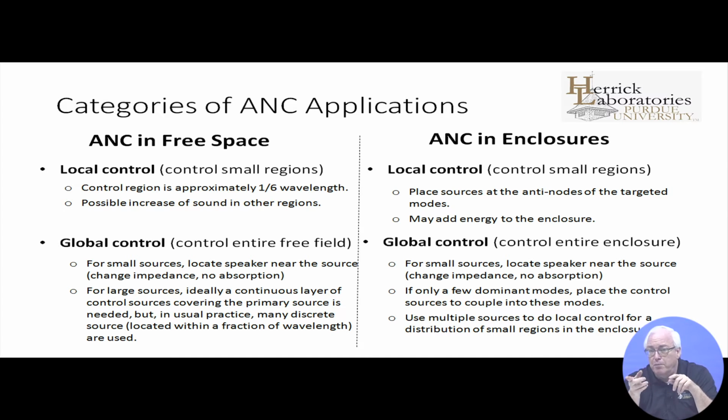Yesterday, we were in the building acoustics section. We were mentioning that often there are various modes in this space, and each of those modes, in a sense, is a way of conveying energy from one spot to another. So in the presence of the modes, you've got a lot of parallel paths from a source to a receiver location. So very roughly speaking, the low frequency approach is to control the modes in the space, and you need enough sensors and enough actuators so that you've got access to each of the modes from an observation point of view and also from a control point of view.